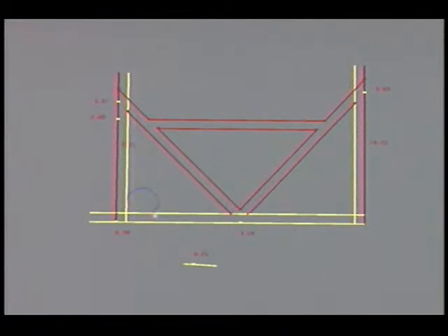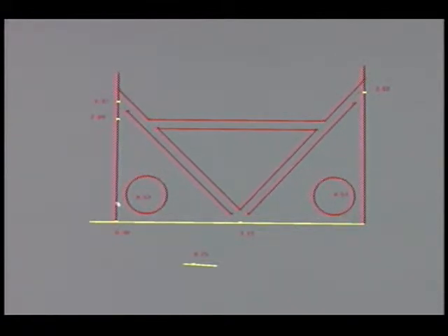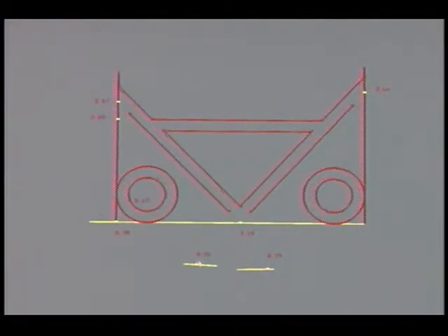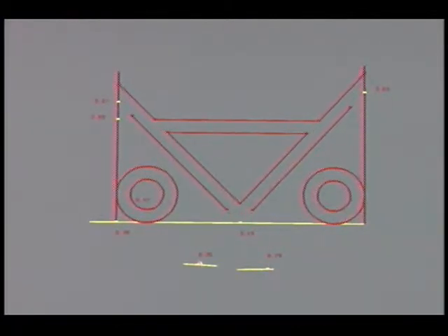Next, the user draws a pair of identical circles tangent to two lines, followed by two more circles, again tangent to two lines. Another slider is created to control the size of the second pair of circles. To set the dimension of the second circle pair, the user first equates both pairs by dropping the radius value of one onto the other, and then subtracts the wall thickness by dropping its value onto the subtract box for the second pair. The user now has a high-level parametrized 2D construction.